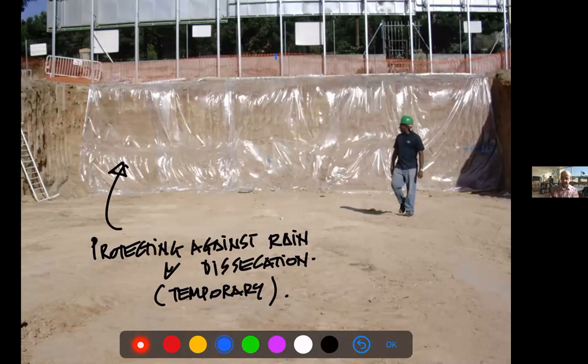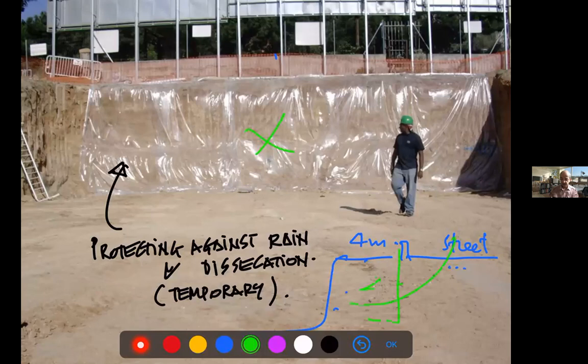And this is next to a street. And in this case, we have the street, right? We have 4 meters, right? And then the excavation. So if something happens, probably the street will not be affected. If we were excavating next to the street, we would not follow this system, because if something happens, you destroy the street. And this is very embarrassing, dangerous, and expensive problem.